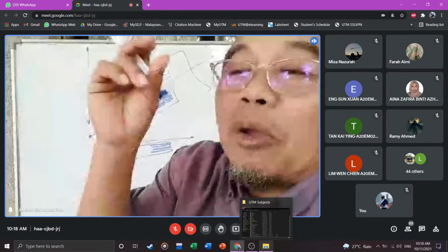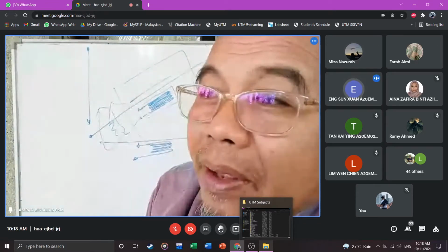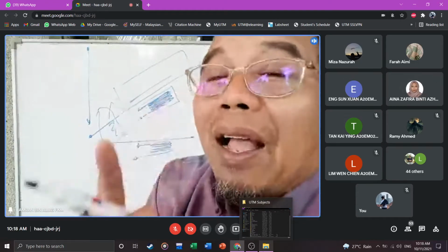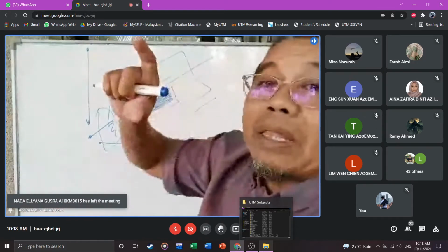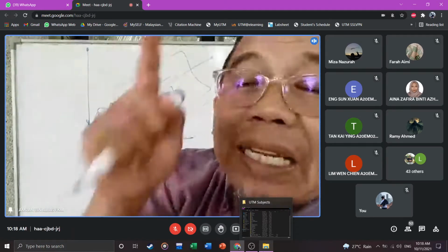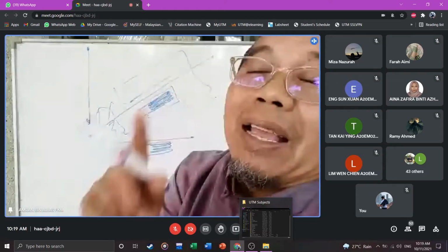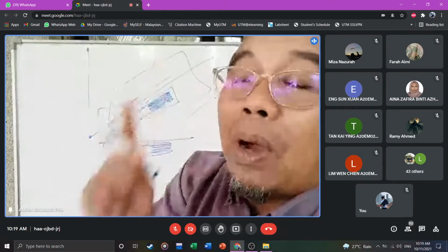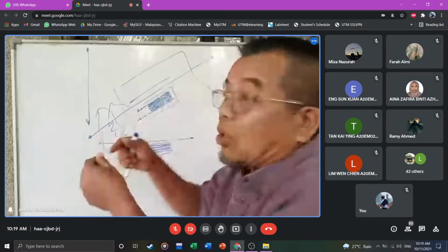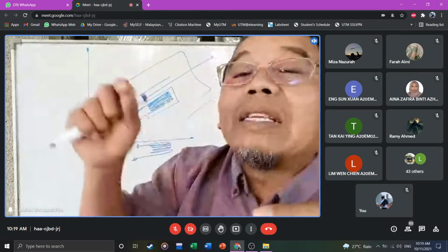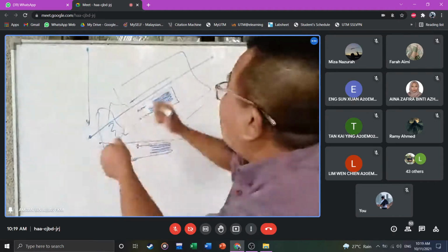What are other phenomena when things extend that way? What happened to the diameter? The diameter decreases. When it elongates in that direction, the diameter decreases. What happened to the resistance in electricity? Increased. Yes. The concept of how it works is about the resistance. When this is being stretched that way, the wire size becomes smaller and the resistance increases.